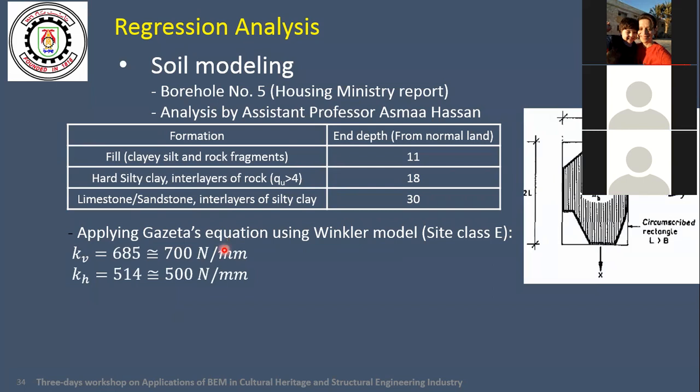And the other improvement we looked into was the modeling stiffness of the wall. Remember, I mentioned there was a stiff wall attached to the mausoleum. So this is the model of the wall, and we applied the horizontal unit load in order to get an estimate of the stiffness for the wall.